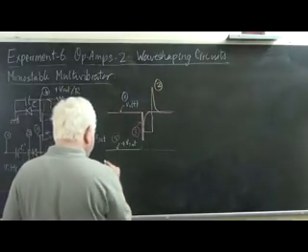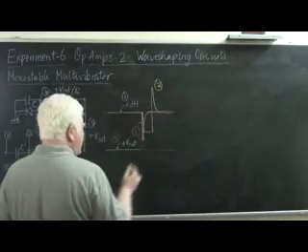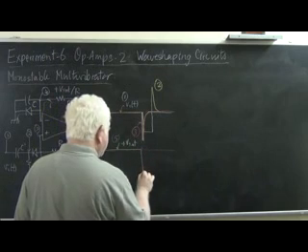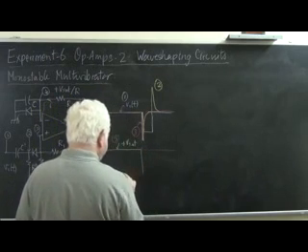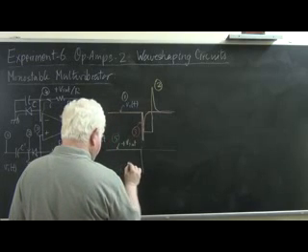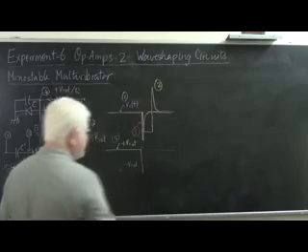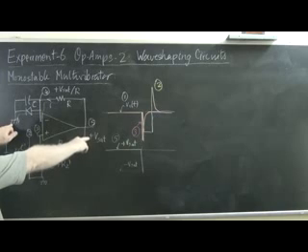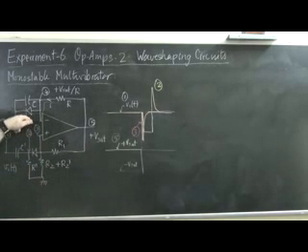And here we have the 0 reference, and at this point, the op-amp output went to minus Vsat. As soon as the output went to minus Vsat, on the inverting side, several things happened. This is now minus Vsat, this is ground. So the diode gets reverse biased and acts as an open circuit.